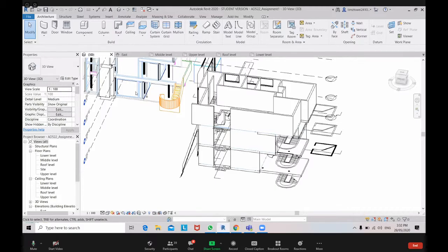Yes. Okay, first of all, activate the solar path first so I can see where the north is. Maybe you did change already. Click on that sun, and then click sun path on. Oh, I haven't changed the sun path actually. Okay, just click use this specific.